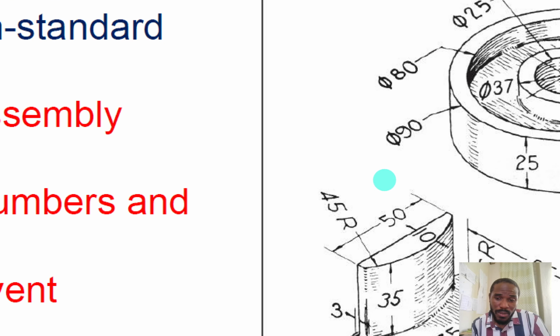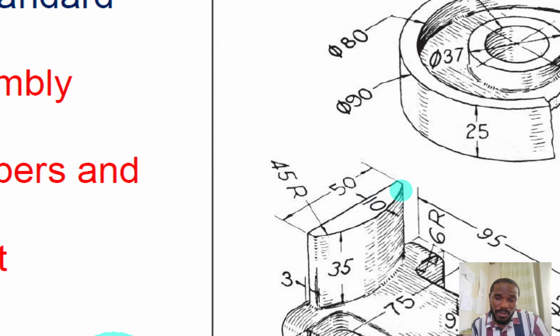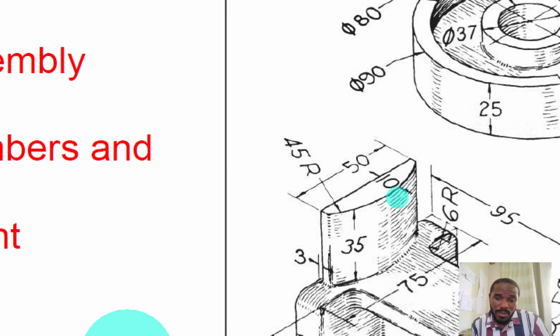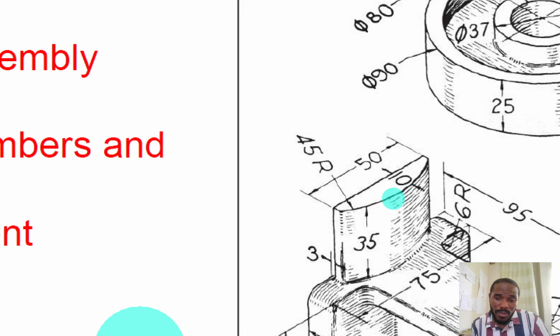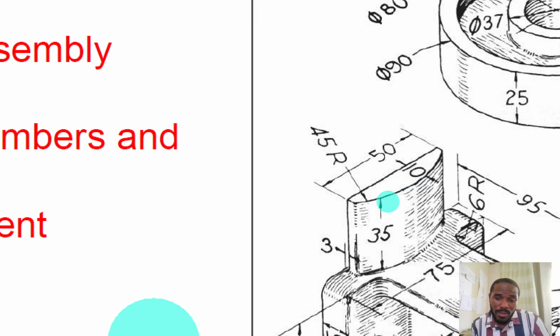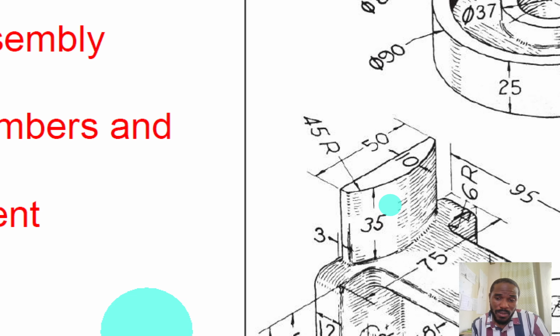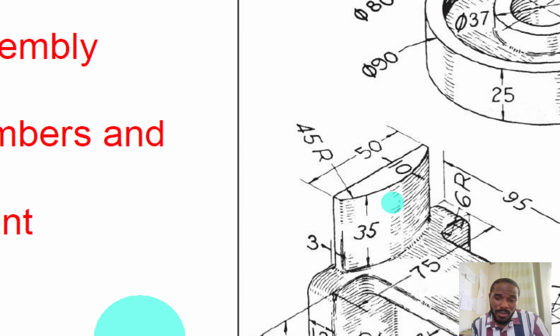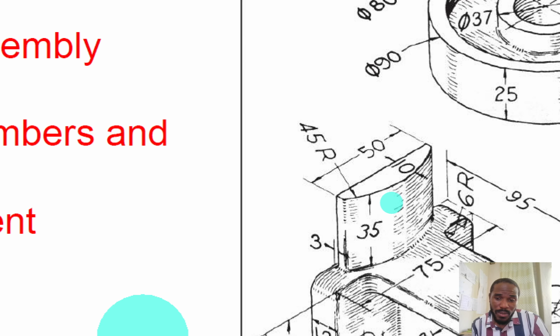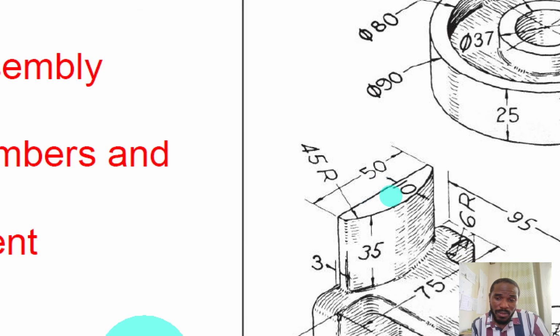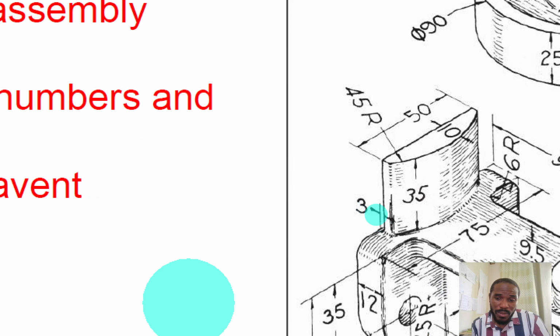And I will do a tangent between that circle and this side of the rectangle that I draw, okay? Once I do that, it's going to fit where it should fit, and then I trim off everything else that needs to be trimmed, making sure that everything is symmetrical, okay? But the bottom of that rectangle has to be 3 millimeters from that.